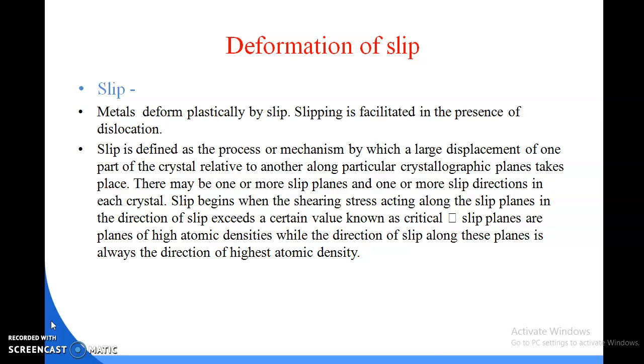Slip is defined as the process or mechanism by which a large displacement of one part of the crystal relative to another along particular crystallographic planes takes place. There may be one or more slip planes and one or more slip directions in each crystal.